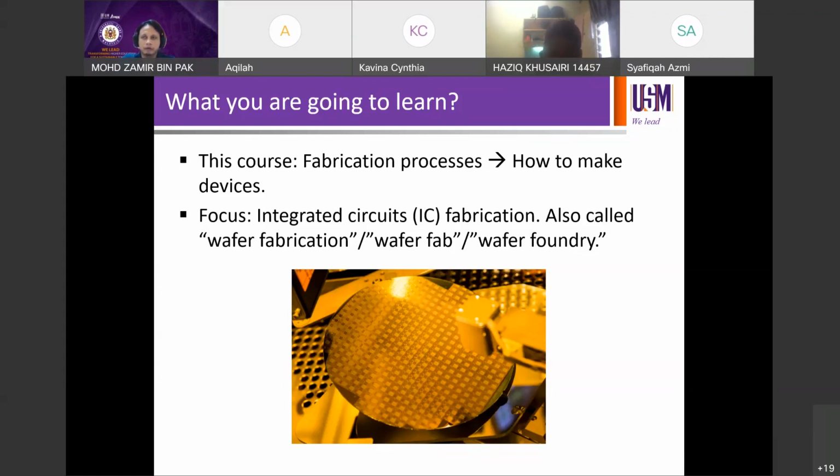So all in all, if you learn the fabrication processes for integrated circuits or transistors, some other devices can be fabricated with even simplified processes. The process to fabricate an integrated circuit is a very complete, very long and very complicated process, but you can just extract the very same processes here and there to fabricate, for example, solar cells, LEDs, solid state drives, and some other devices as well.